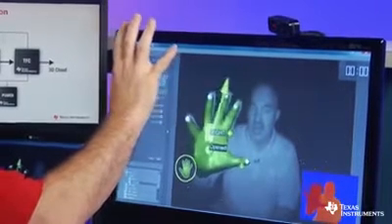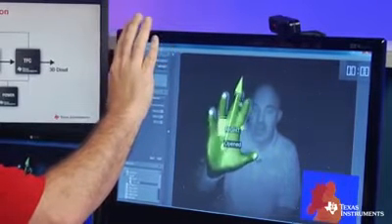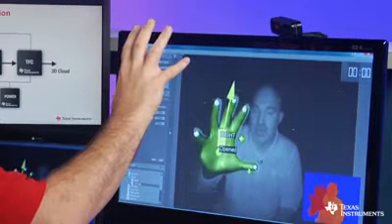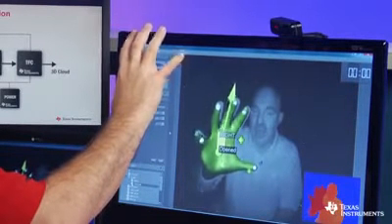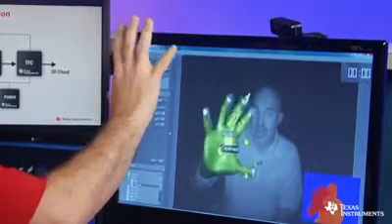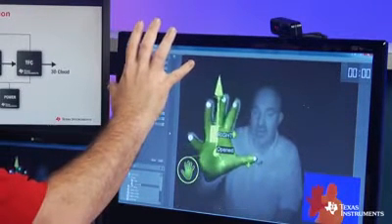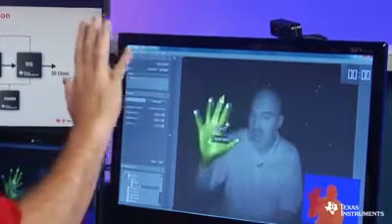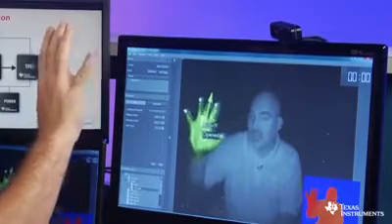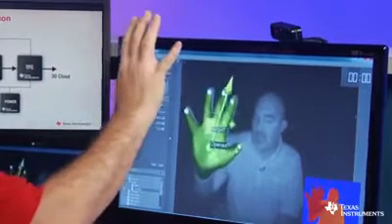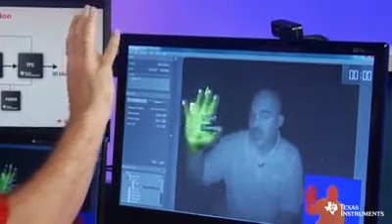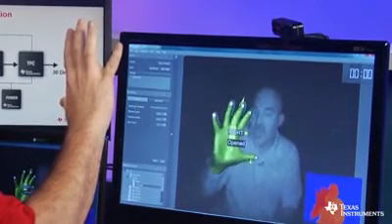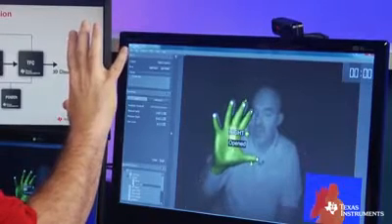In addition, TI's depth sense pixel technology does a lot of the pixel processing in pixel, which enables it to free up the back end for gesture recognition as opposed to pixel processing, which enables an overall lower system bill of material cost. You can see in the bottom right-hand screen the actual depth map itself. So as I get closer, I get darker. As I get farther away, I get lighter. So this is actually the measurement of what's coming out of the pixel sensor itself in terms of the depth.